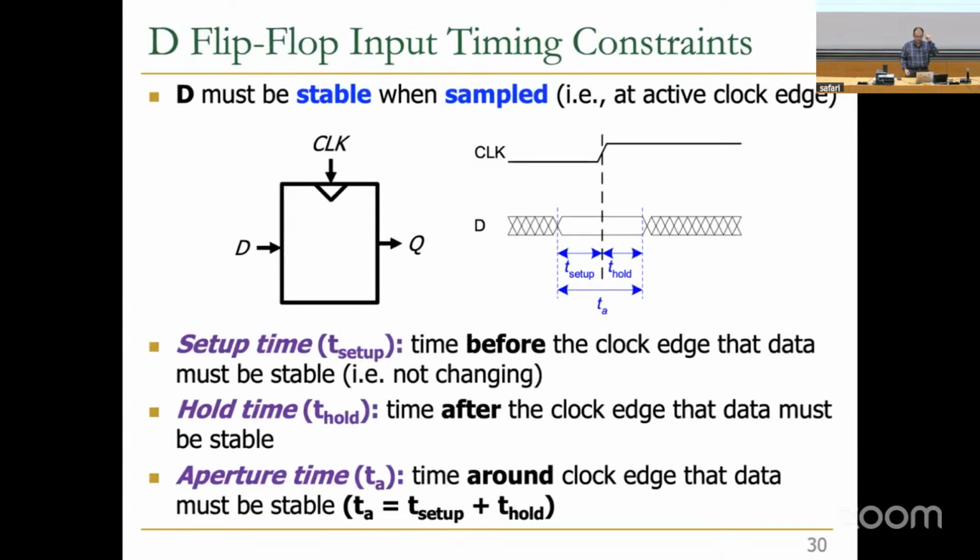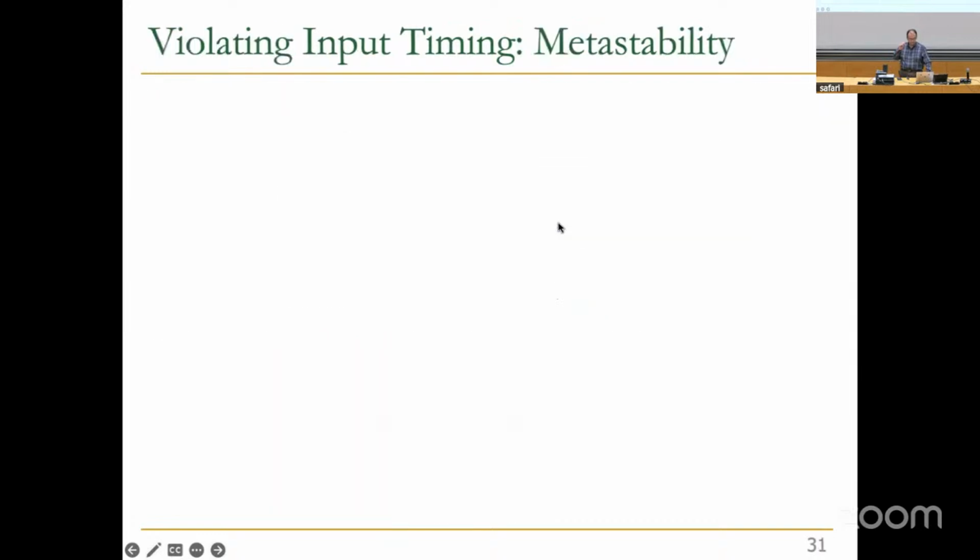What is the signal in this part, is it don't care or float? You're saying the D is changing, because there might be a combinational circuit driving the D data here. So that circuit is causing D to change. There might be a lot of changing here, but I don't care. What I care about is that from this time, D should be stable. Any other question?